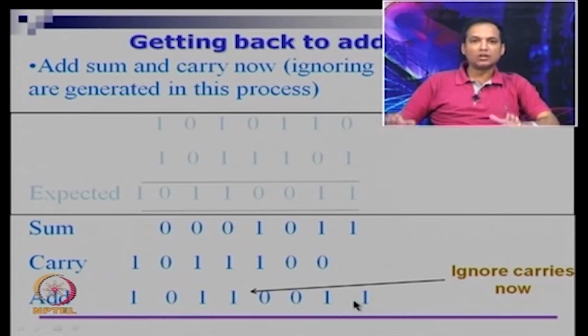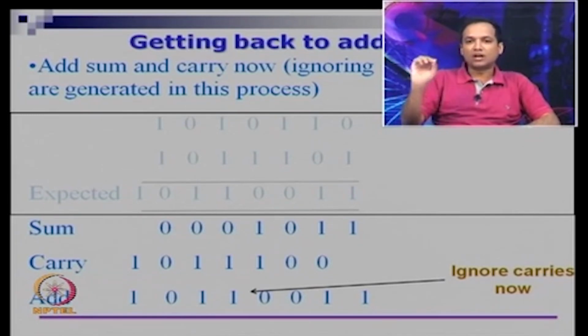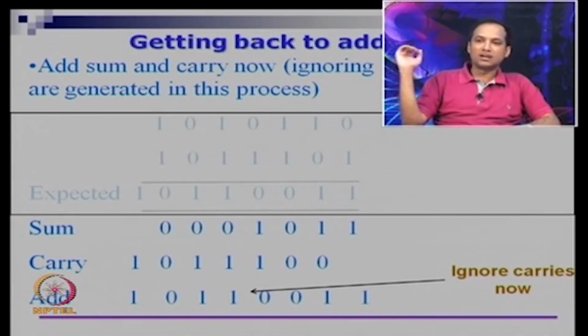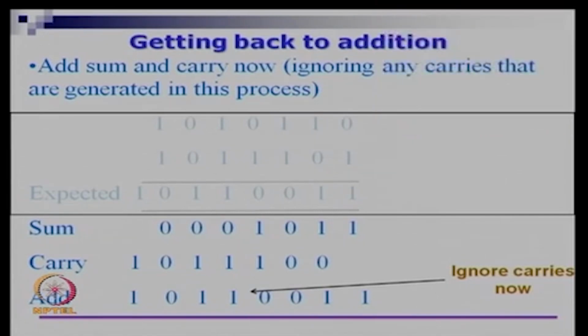you will get the final sum. So all of this may look like magic, but if you follow through the steps carefully, all I have done is follow the same idea as in the parallel prefix circuit. In log n steps we have resolved the carry condition instead of the n steps that we required in the ripple carry setup. So this is a fast adder, because as n grows your delay is not growing linearly with respect to n, it is growing only logarithmically with respect to n.